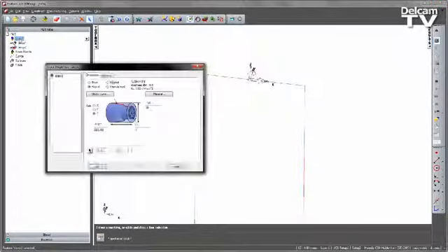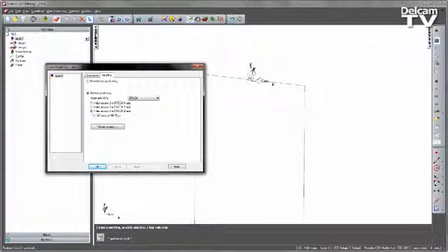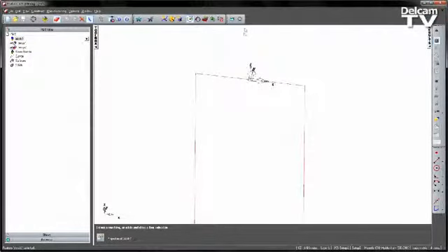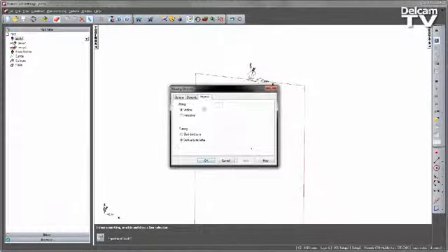As well as this, under the stock dialog, under indexing, you'll notice there is a new checkbox called vertical mill turn. This is enabled when we use this vertical mill turn type document. We also get a toolbar which appears with a couple of utilities that allow us to post the mill turn setups as a combined NC program. And in this demonstration we're going to look at the simulation combination as well. It's recommended under the viewing menu, under machine, you switch your turning machine to a vertical turret lathe to represent the view controls a bit more realistically when we're dealing with any kind of machine simulation.